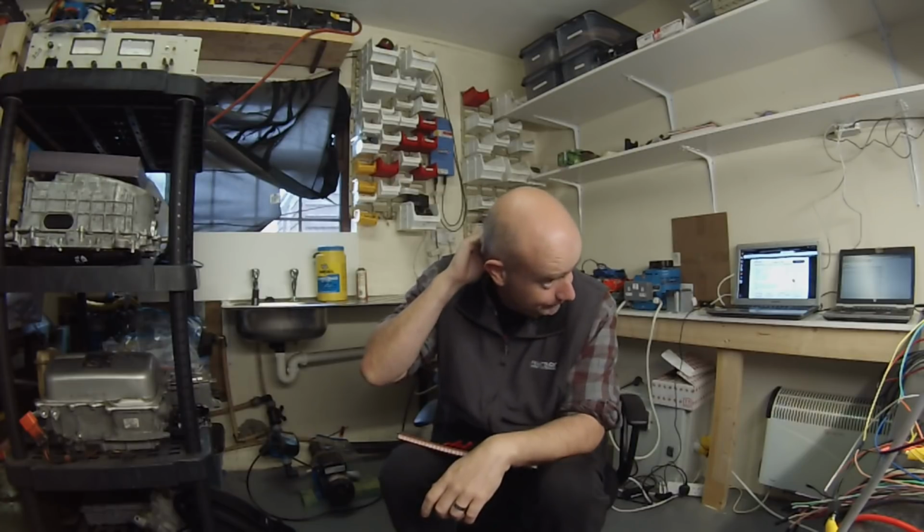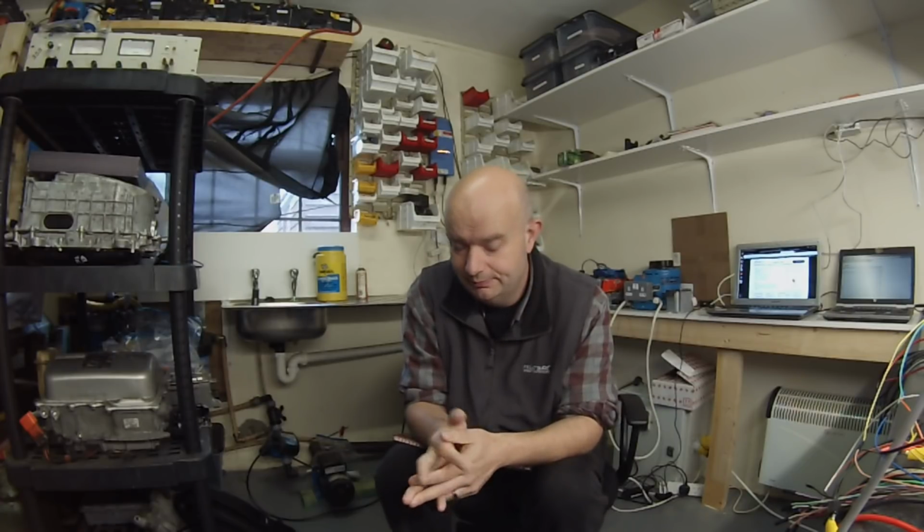Our problem is that our analog current sensor circuit is not doing anything wrong, and our cycle by cycle current limiter isn't doing anything wrong, because if you set the cycle by cycle current limit to 850 amps, you could drive the car all day long. Okay? You set it to 900 amps, it shuts down because it trips the hardware. But at 850 amps, it's sufficient to keep the current peaks below the trip point of the analog circuit.